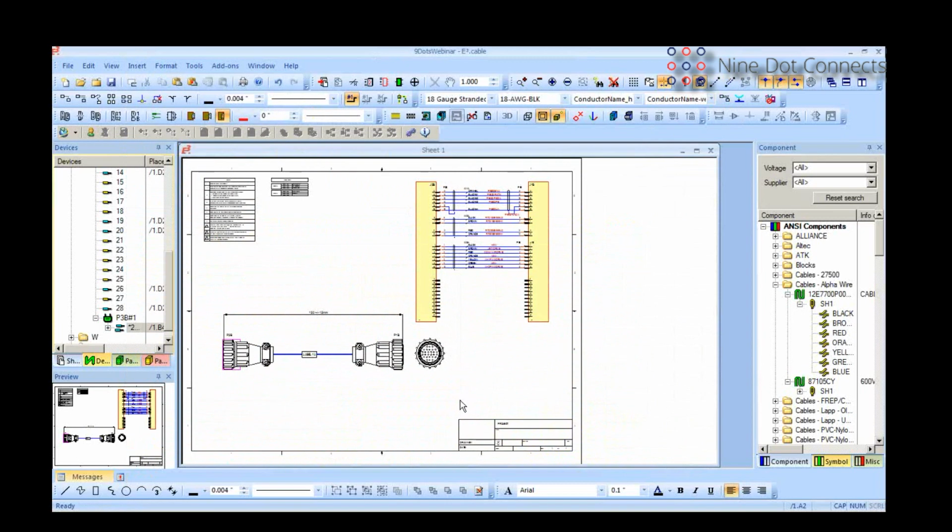Now, let's look at the scenario of where I got the length from. In this case, I've just put in a length into my example here. But as far as the tool's concerned, I can develop all of my interconnections. I can define the harness with all of the components of the harness, the back shells, the terminal pins, any labeling, any type of cable protection that I want. The thing that I really don't know, other than by putting it in manually, is the length information.